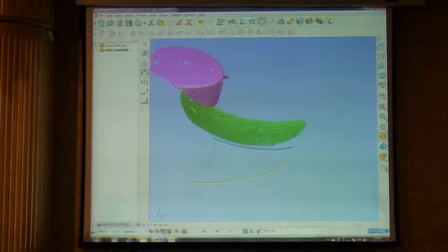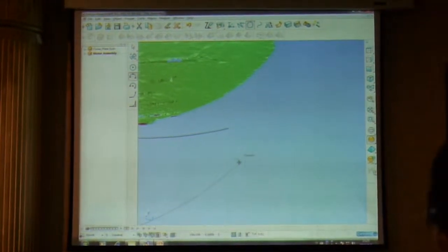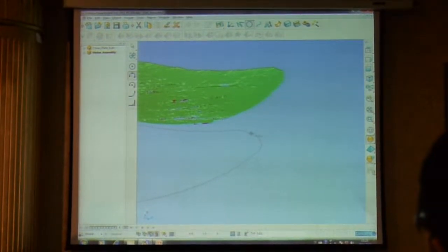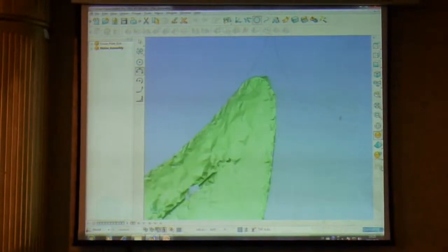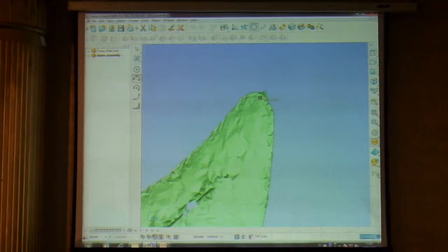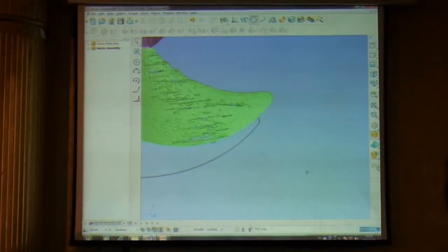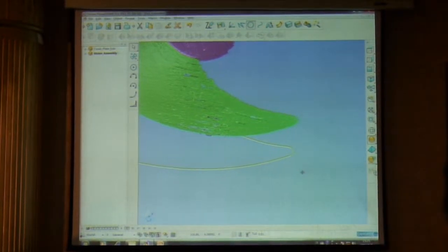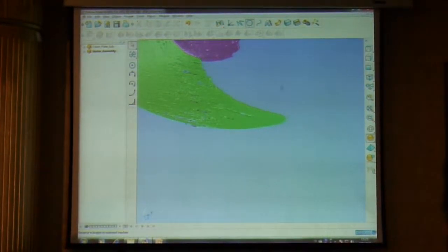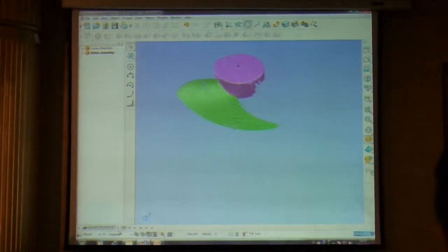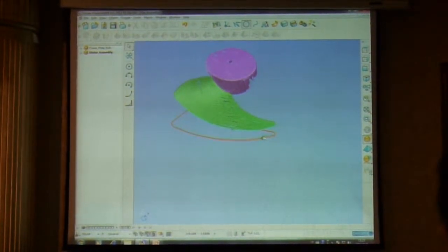And you'll notice that PowerShape has a very powerful, intelligent cursor. So the cursor's continually giving me feedback about tangency and point information. Okay, and I can confirm the radii to construct good quality geometry around the edge of the blade. Okay, now I have the finished profile stored on a level, so let me turn that on.